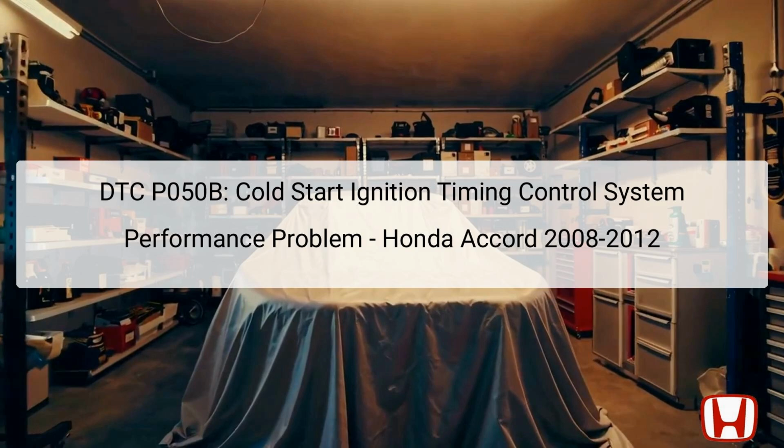This code is associated with components such as the crankshaft position (CKP) sensor, the engine coolant temperature (ECT) sensor, and other critical engine management sensors. Before beginning troubleshooting, it's important to record any freeze data and snapshots that may help inform the diagnostic process. The steps outlined in the following slides will guide you in identifying the root cause of the issue and restoring functionality to the ignition timing control system.